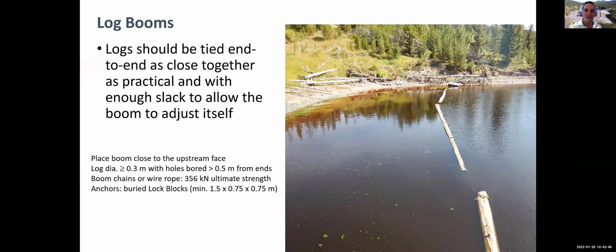So here we see some log booms are getting pretty tired. They're starting to sink. This is pretty typical. They may still work just fine, but you do want to stay on top of them. On the bottom left, that is a spec right out of the BC plan submission guidelines for repairs or new dams. They put a spec right in there because they have so many questions. So why not use it, right? And you can deviate from that. Some people have better luck with slightly changed, but anyway, there's one that the BC guidance just gives you.